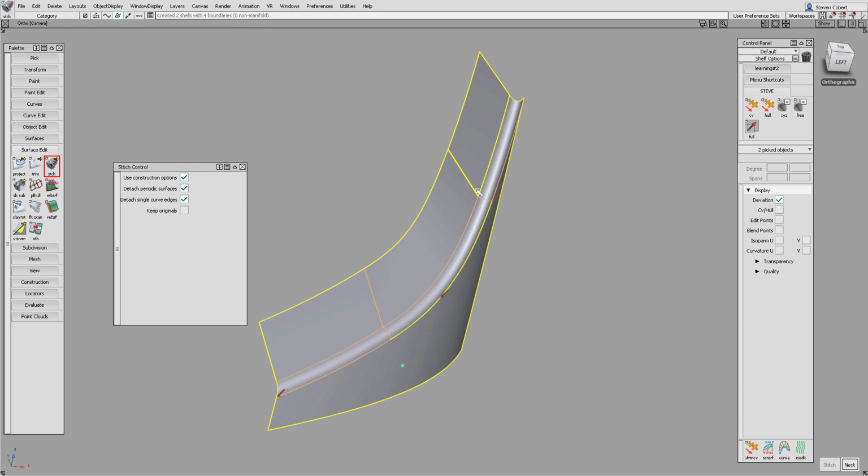If you look at the yellow edges here, that's showing 3 edges, so it's thinking that that's one separate part there, and then we've got another part here which has got 3 edges or yellow lines all the way around it, and then there's also a split in the middle, so another yellow edge there which shows that there's a gap bigger than the 0.0009 that we want.